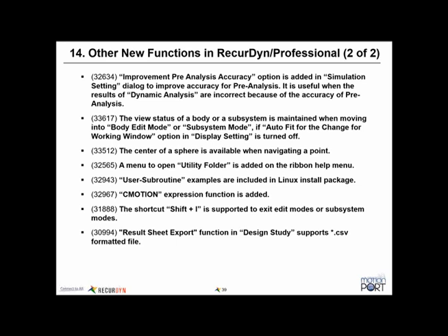In the past, every time you switched between levels in the hierarchical tree in RecurDyn, in other words, went between main level and the subsystem, main level, body edit, or whatever, it would always do this auto zoom or auto fit. You can actually turn that auto fit off, and then it won't keep changing things on you. That's just another option under display settings, so you can go there and you'll easily see where that option is now present.